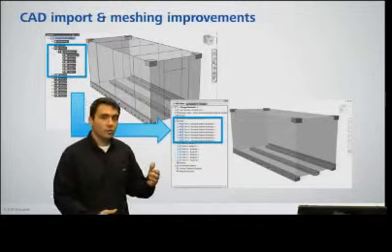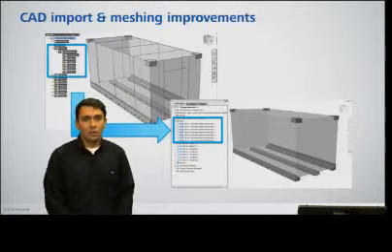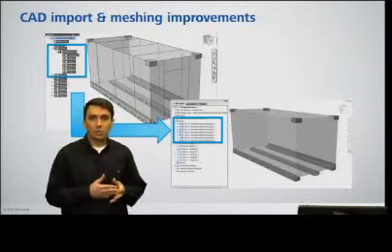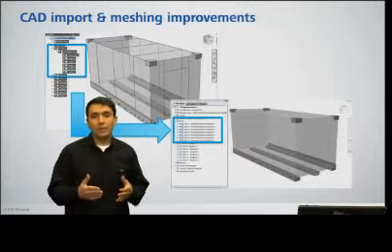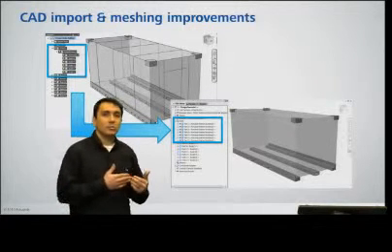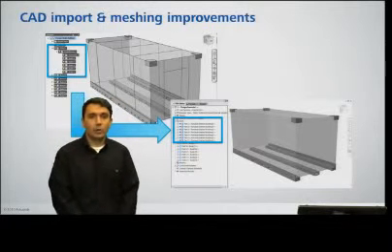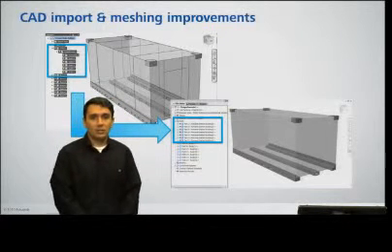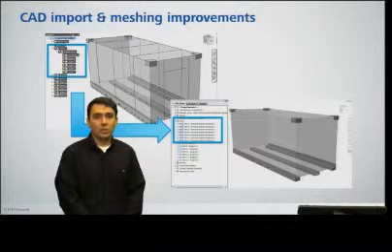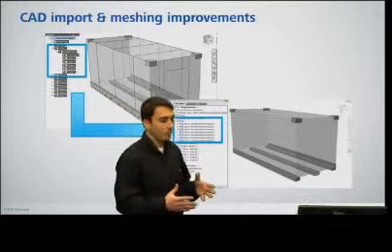In the 2014 release, we've implemented a capability to delete mesh, which will allow you to select a certain part or a group of parts and delete the mesh associated with that and clean your database to start a simulation from scratch. This was a common enhancement request from our user base and will be beneficial to those advanced users who want more control over their mesh structure.